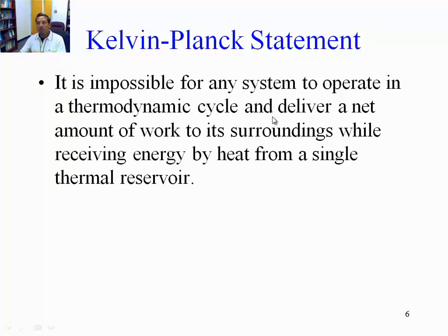It is impossible for any system to operate in a thermodynamic cycle and deliver a net amount of work to its surroundings while receiving energy by heat from a single thermal reservoir. That means that you at least need 2 thermal reservoirs in order to produce energy in the form of work, in order to produce work.